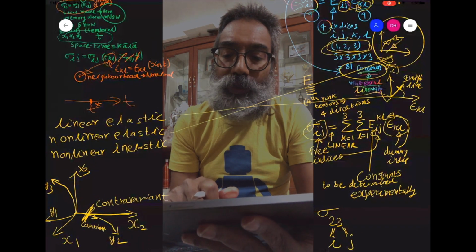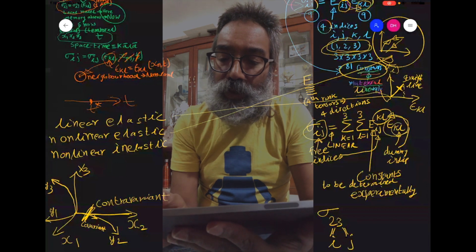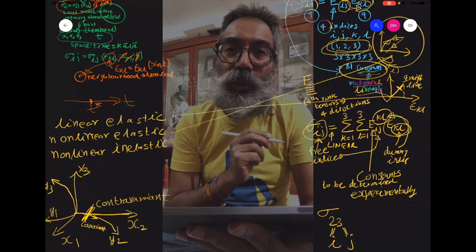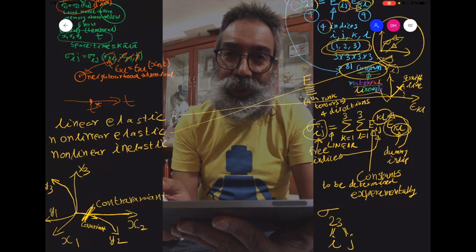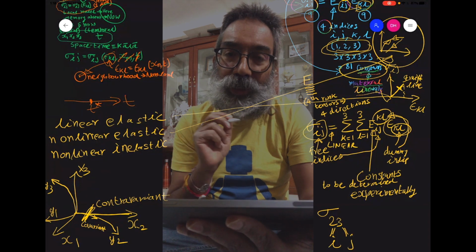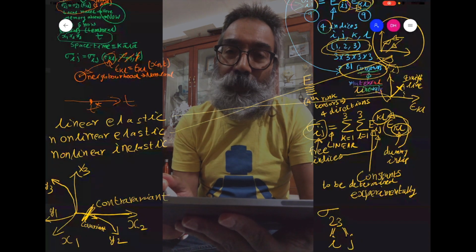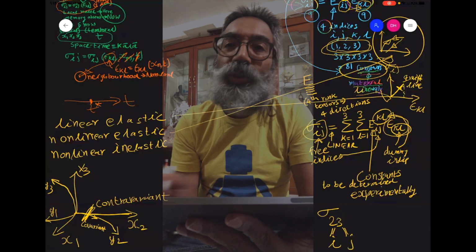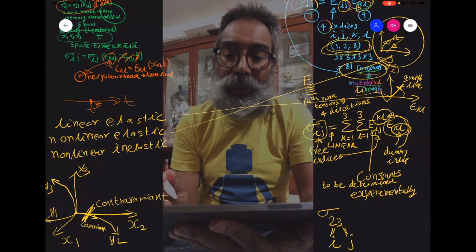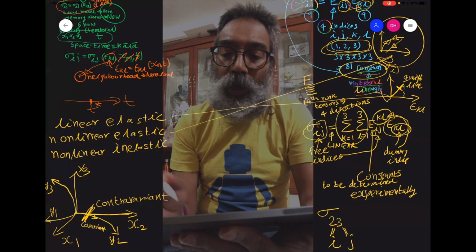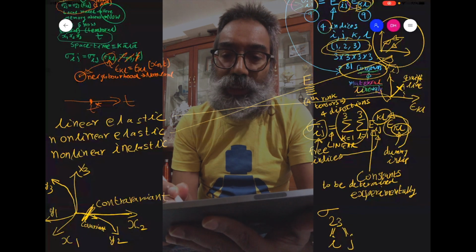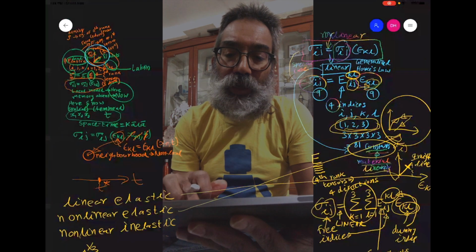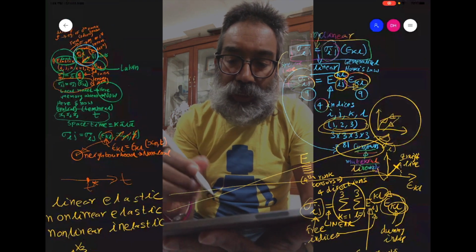On the other hand, these are dummy indices, KL, that you see in the superscript of E as well as a subscript of epsilon. Because they are repeated, there is an implied summation according to Einstein's summation convention, and therefore they are dummy, because you're only using them to say that you have to sum over their entire ranges, which in this particular case happens to be 1 to 3. So even when I do not write these summations explicitly, that's what is understood. So you do not need to specifically mention that, which is what this form of the equation is.